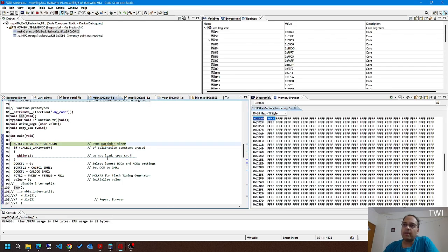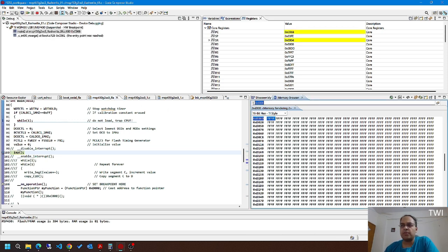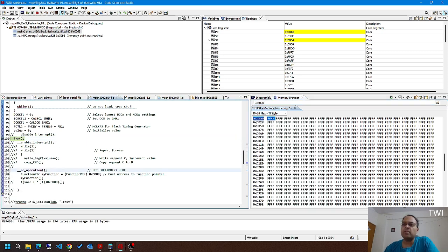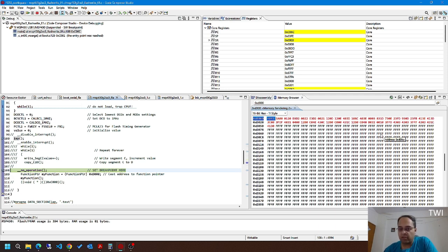Right. So now I can give you a breakpoint analysis. Once it comes to the IAP, on the right side I have kept the memory map of D000. Right now you can see this D000 is fully erased and it doesn't have any code. Once the IAP is executed, it should be writing the entire memory, which you can see in red. The updated firmware, which was there in the array, which should come from Wi-Fi, from your Git, or the server from where you want to update your device remotely, that code comes and sits in this location.